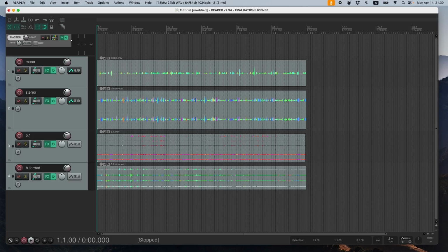So the signal chain overview is first the audio signal, then this goes to encoder, and the encoder creates a B format. It's usually 64 if you're working in 7th order, and that goes to decoder, and from decoder it goes to headphones or speakers. And the order always matters. If the chain is not correct, it simply doesn't work.